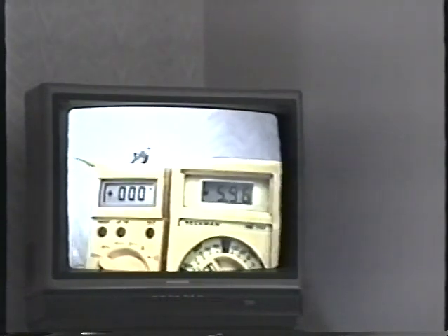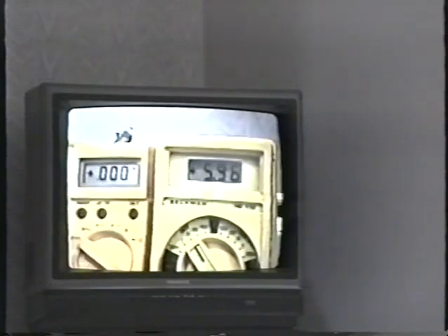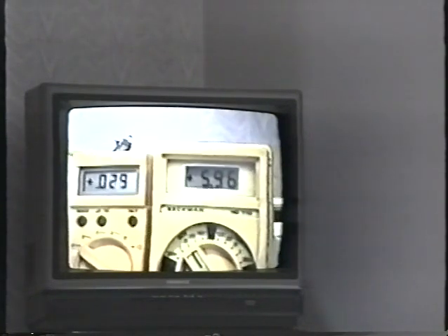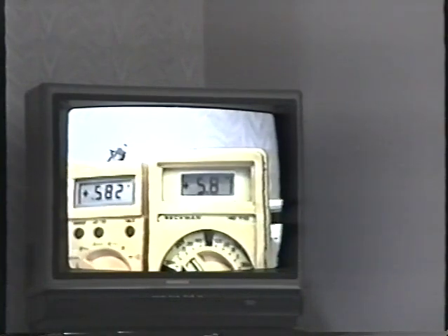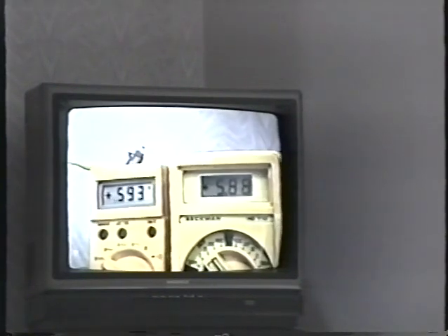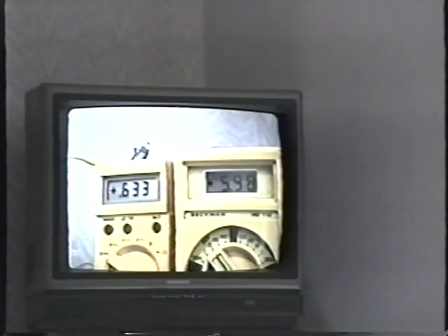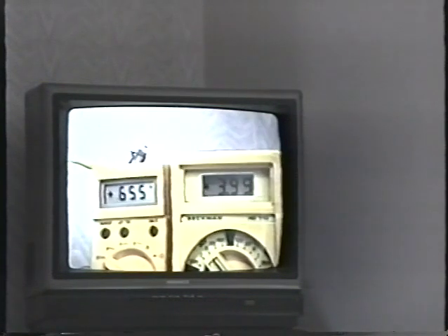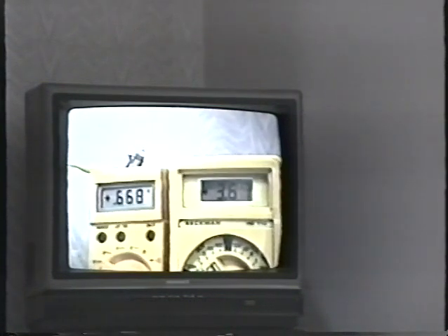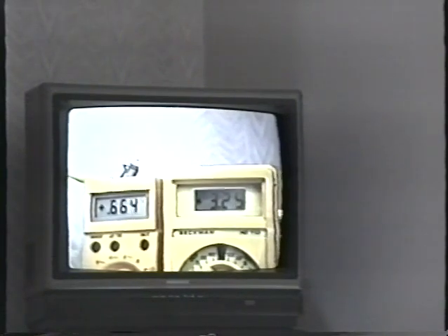Let's watch what happens as I increase the base voltage. And what we're looking at is the lamp, the base voltage, and the collector voltage. All right. Let's start to increase the base voltage. 0.1, 0.2, 0.3, nothing's going on. Nothing's happening. Now look, right here, let me back it down a little bit. At about 0.5, watch the collector voltage. It's going to start to drop now. See the collector voltage start to drop? 4 volts now. You see how the lamp's a little bit dim? It's starting to come on now. The base voltage is going up. The collector voltage is dropping.